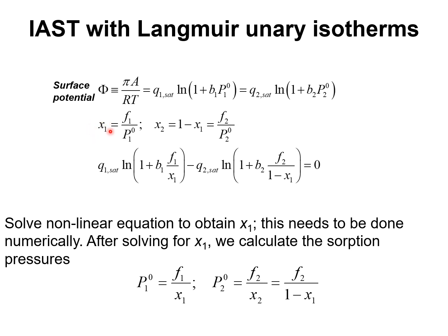We also have the relation between the mole fraction in the adsorbed phase and the sorption pressure for component 1. The mole fraction of 2 in the adsorbed phase, which is equal to 1 minus x1, is related to the sorption pressure for component 2. Inserting these into the expression for the surface potential, we obtain the following relationship.